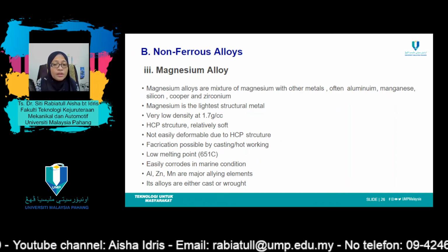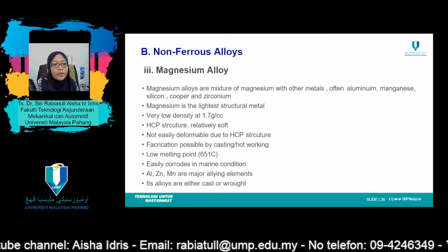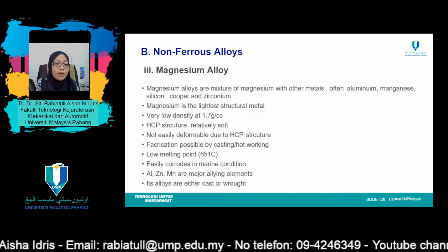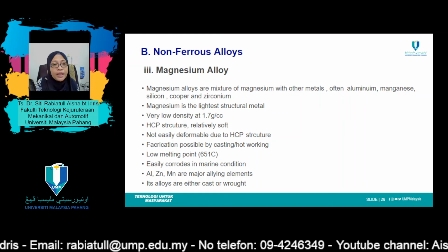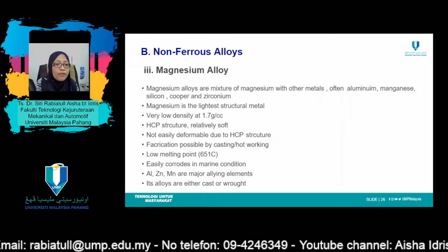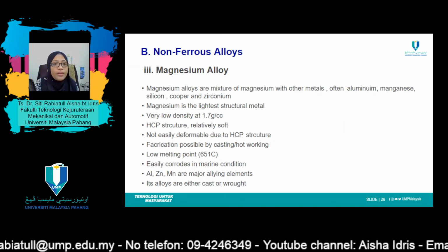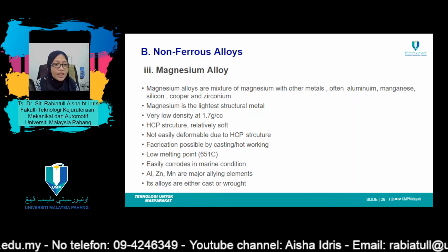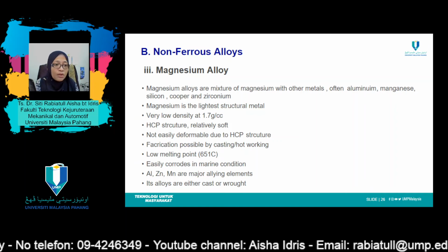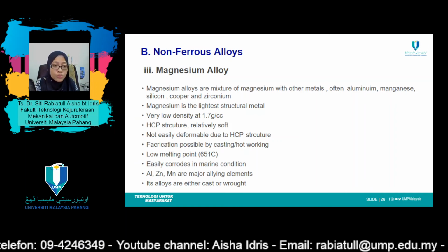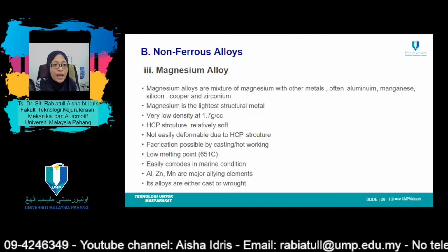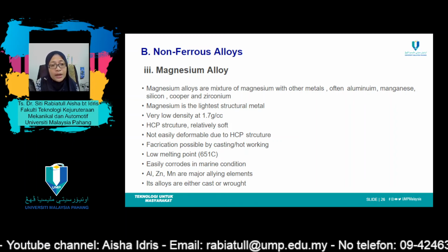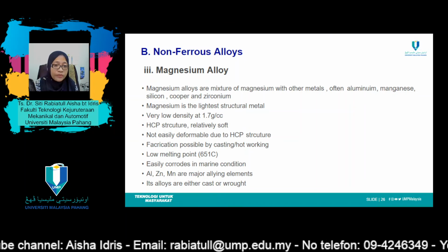These magnesium alloys are classified into either cast or wrought, and some of them are heat treatable. Aluminium, zinc, manganese, and some of the rare earths are the major alloying elements. A composition temper designation scheme similar to that of aluminium alloys is also used. Furthermore, in the last several years, the demand for magnesium alloys has increased dramatically in a host of different industries.